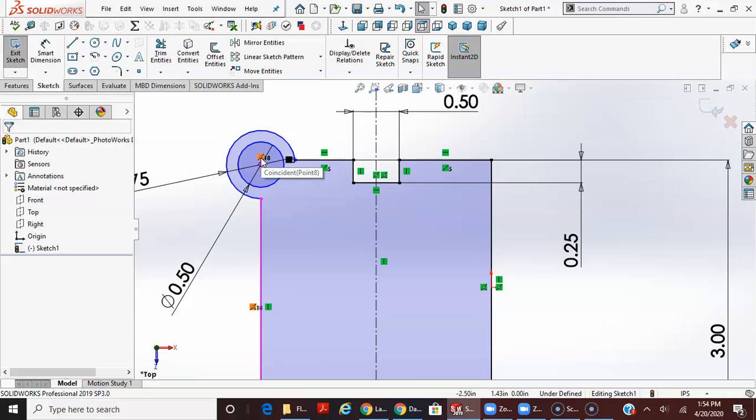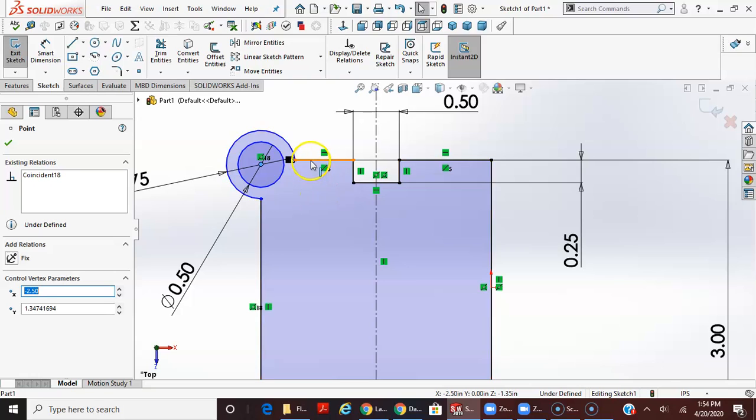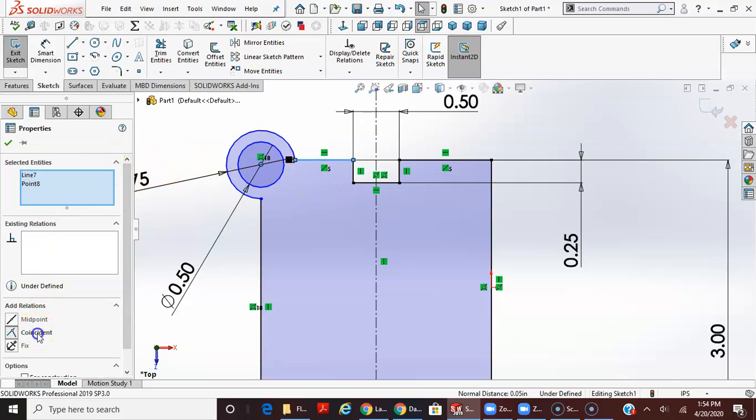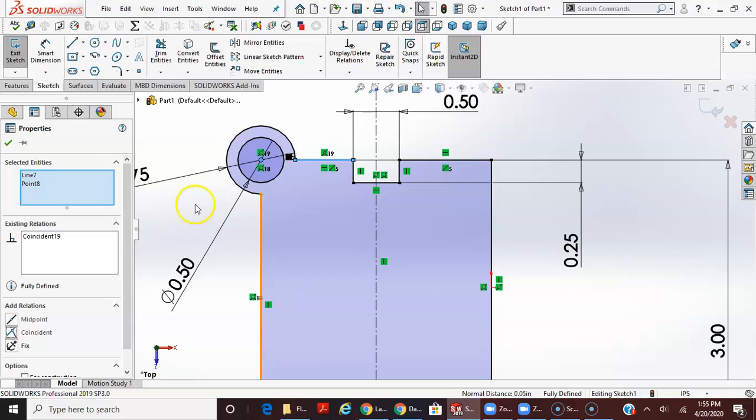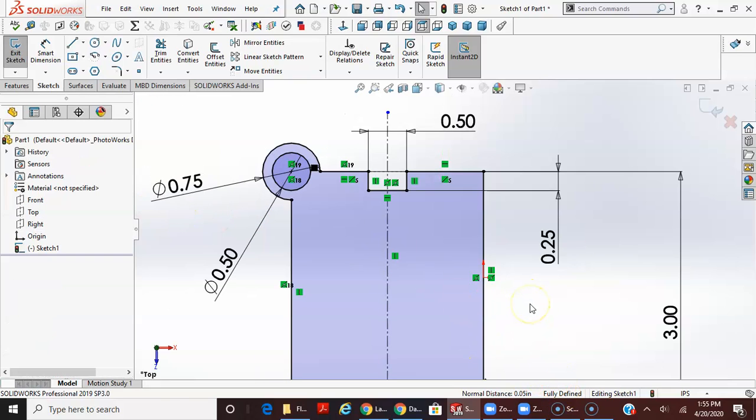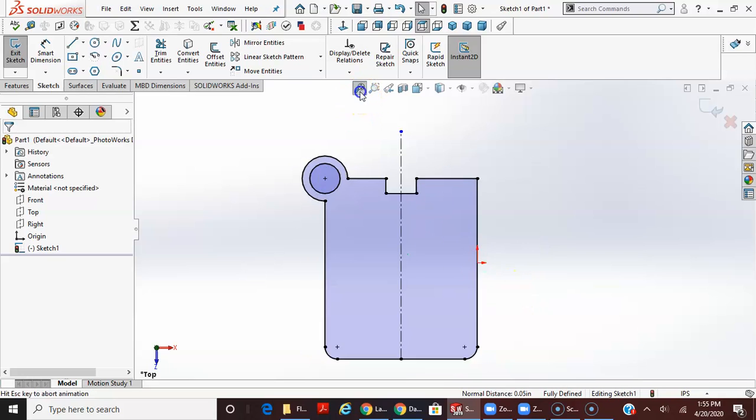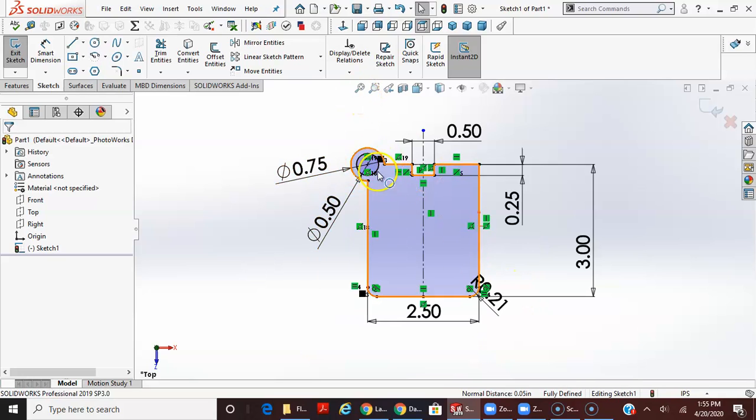It's the same as this coincident point, but I'm going to add it coincident to this top horizontal line. So I'm going to select point, control point, and make these coincident. Now it shows down here as fully defined. So the midterm has an issue like this, maybe even more than one.